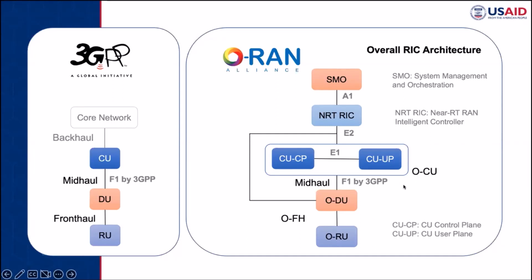As we have also seen in the previous slide, in the functional split, basically the RRU will just be in charge of the lower part of the physical layer or the whole physical layer, and then the baseband unit, this part here or the distributed unit, is in charge of the processing, the MAC, and the CU is in charge of the upper network layer protocols.